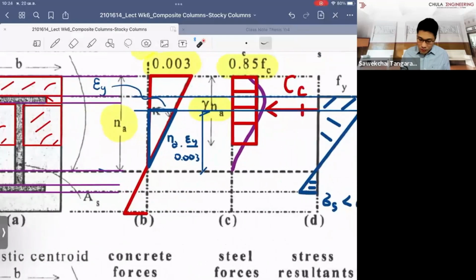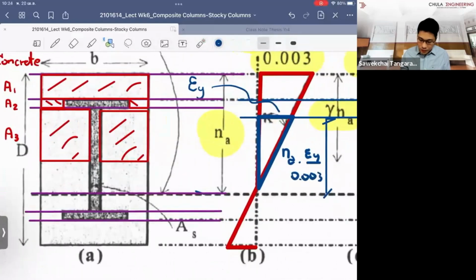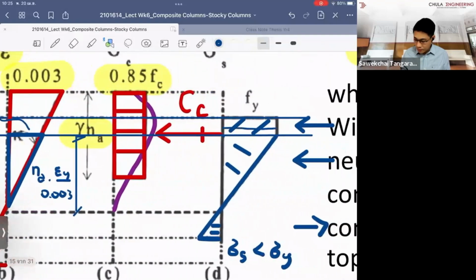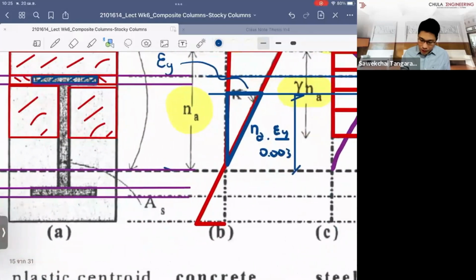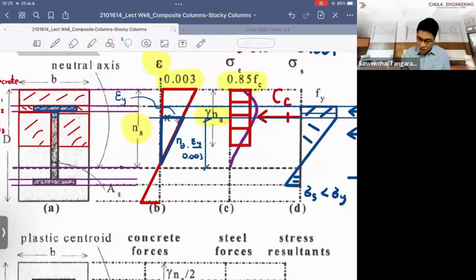So what you do, you have to find first, based on the top flange in the steel, and normally for this we develop what is called the yield stress in the top flange, and you find some part in the web of the steel where it still develops the yield stress, right? I didn't want to draw the line and keep running the line through.